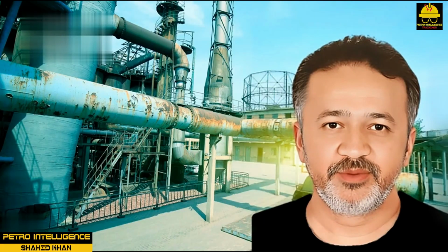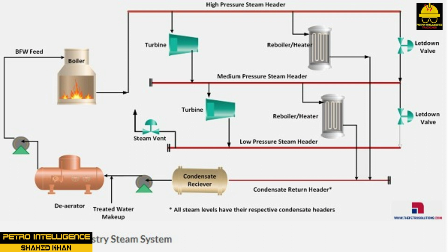High-pressure steam system, 400 to 800 psi. HP steam is supplied as required by lowering the pressure from the SHP header. High-pressure steam extracted from steam turbine drives can be used to feed the HP steam header. HP steam may be imported from other units into the high-pressure steam header to maintain overall steam balance.